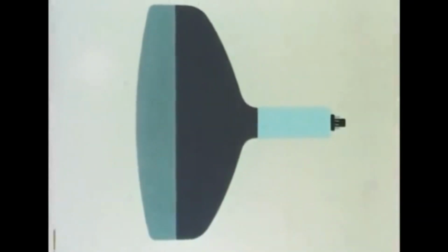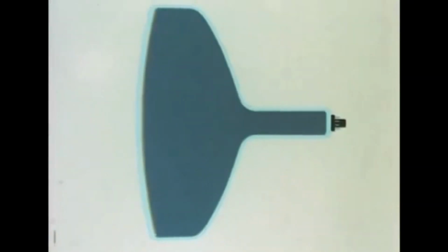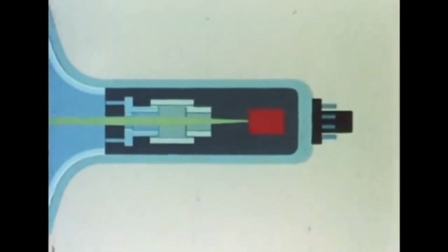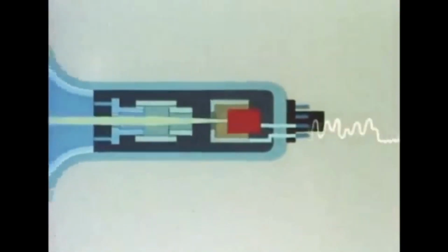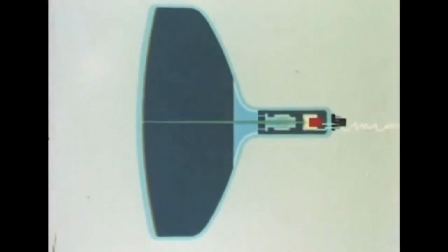In 1977, the cathode ray tube, or CRT, was the dominant display technology. You may remember these as TVs. A CRT is a vacuum tube with a large, flat face leading to a thin neck. At the end of the neck is an electron gun where a heated cathode emits electrons into the vacuum. An anode charged to tens of thousands of volts attracts the electrons and sends a beam of them flying towards the face, which is covered in phosphor, a substance that emits light when bombarded with electrons. The strength of the electron beam is controlled electrically by the image waveform we talked about earlier.